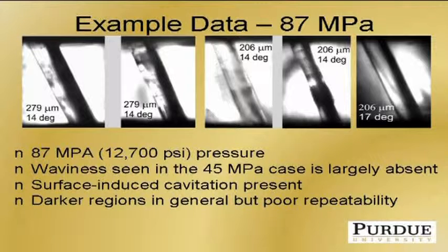These are some pretty pictures here. You're seeing there's something going on along the right-hand side there. A type of cavitation going on there. You're seeing some surface roughness effects show up here and there. These are different; the left two are slightly larger orifices. These two are 206 micron. And just going down a little bit in length scale, you're seeing different phenomena. And we saw basically three types of cavitation going on. So again, true pressure, true scale.